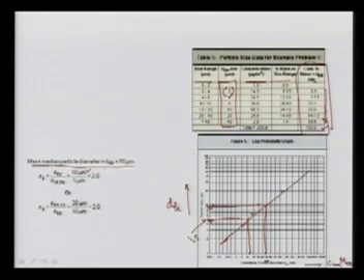Then I can take this value 5 and find out the geometric standard deviation as 2. You can do it on the other side also. You can take D50 and D84.13. If I take 84.13, that also will give me the same thing. So this is 80 here, and this point is 90, so in between, you are getting the answer 20, you can see here 20. So I can take the 20 here, 20 by 10, that will still give me the same answer.